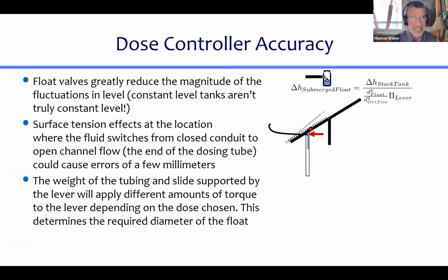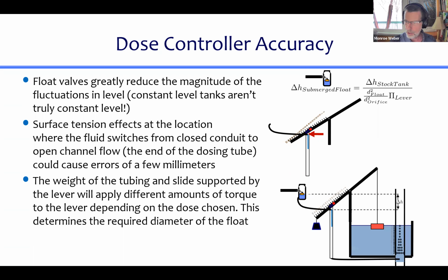And what's resisting that motion at the other end of the lever, there's a float, and that float is hanging out in the water. And when you move that float up and down in the water, you get a force that's related to the change in depth times the surface area of the float and times the density of water and times gravity would get me a weight.